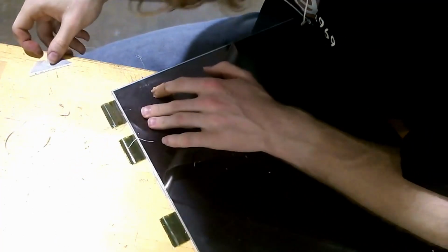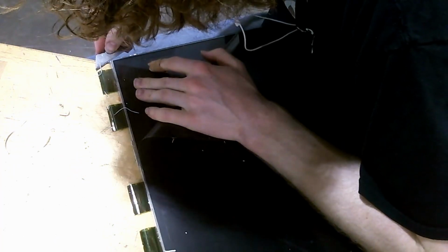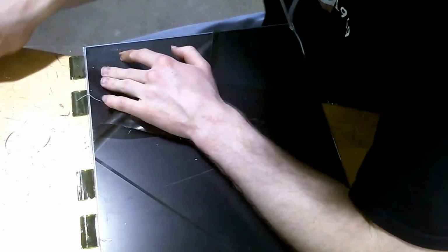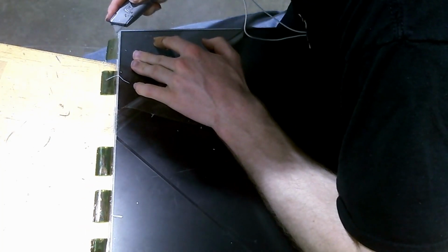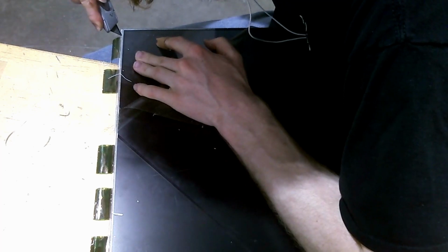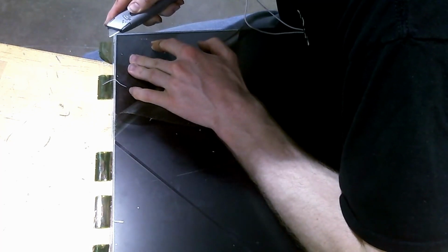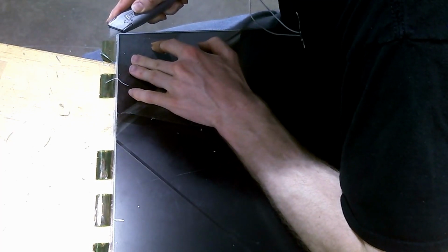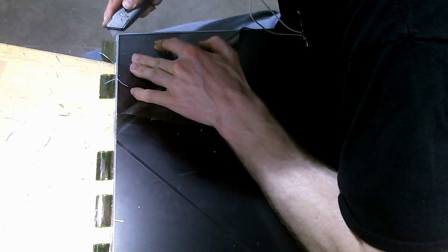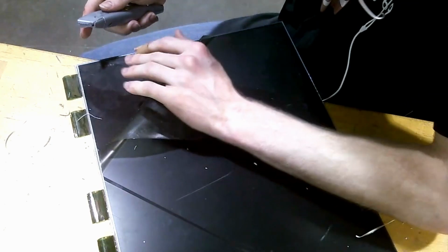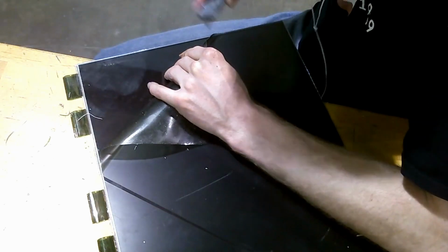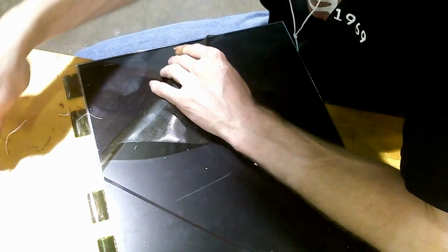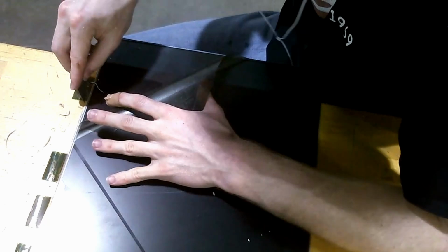In this clip, you'll see I'm trying to work an X-Acto knife blade in between the two panels of glass, and I had about a 7 out of 10 success rate with this as far as monitor screens went. I had a lot of trouble working that knife blade in between the two layers of glass, and usually it would come as like a revelation moment.